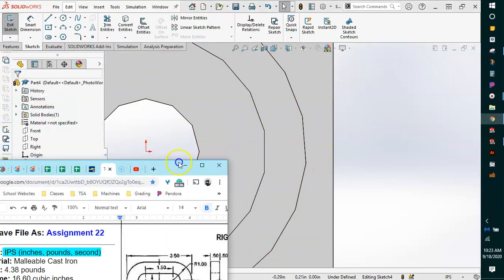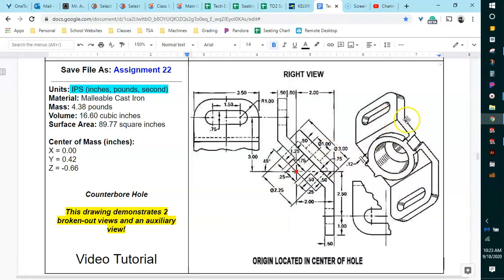Now, these little connecting pieces or these small extra pieces are a little bit confusing to draw because we're working on making sure it's actually inside of the circle. So you can kind of see it does go out straight. There's a little thickness of a piece, a little thickness of a piece, and there's a cutout in here. So we're going to be doing this in 2 steps. The first step is kind of just drawing the overall rectangle and then trimming, so we have this removed to extrude back to here. But we do have a solid thickness there that we're going to have to cut off afterwards.